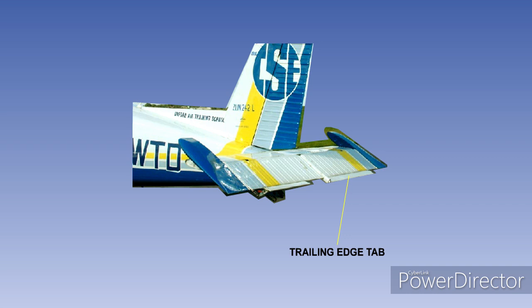All of the previous solutions provide balance by causing some of the pressures on the control surface to act forward of the hinge line. Stick force can also be changed by small aerofoil tabs positioned at the rear of the control surface, but these do alter the effectiveness of the flying control. There are four main types of trailing edge tab device.